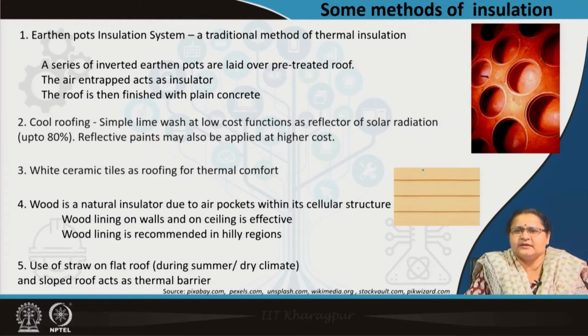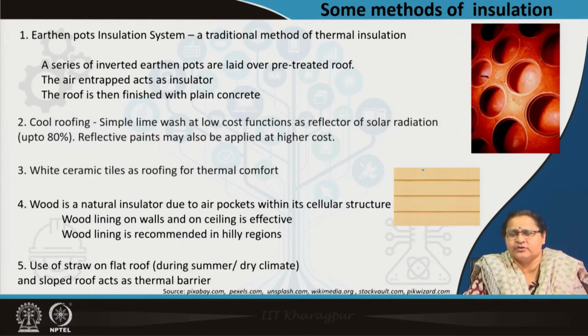So, what you see like tin roof or asbestos roof are really not the answer, because they trap a lot of thermal energy, but the cushion with straw is filled with air pockets. So, those are actually helping in the insulation. So, you have to keep your eyes open and find out what is the purpose of the material and why people have adopted it traditionally.